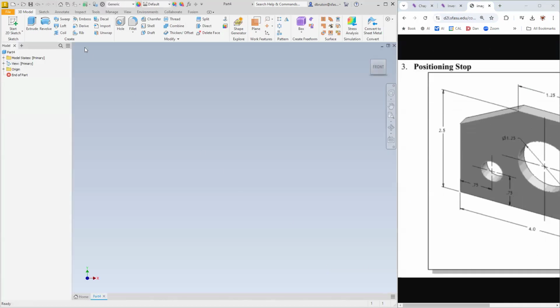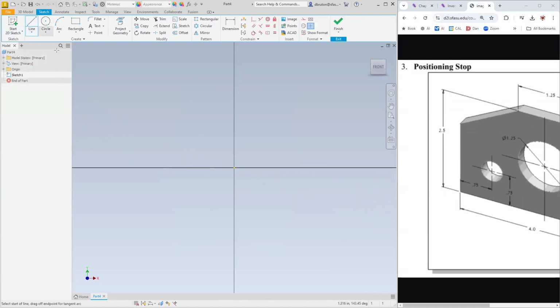The 4 inches along the bottom is a good place to start. And we'll use this axis right there, or that plane rather, the XY plane. Clicking here, and then we're not going to click a second time. We're going to type in 4 and release.